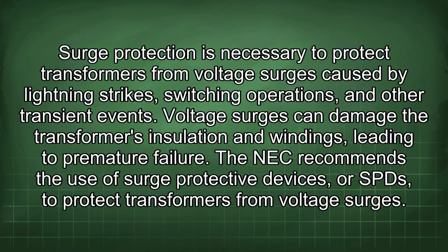Surge protection is necessary to protect transformers from voltage surges caused by lightning strikes, switching operations, and other transient events. Voltage surges can damage the transformer's insulation and windings, leading to premature failure. The NEC recommends the use of surge protective devices, or SPDs, to protect transformers from voltage surges.